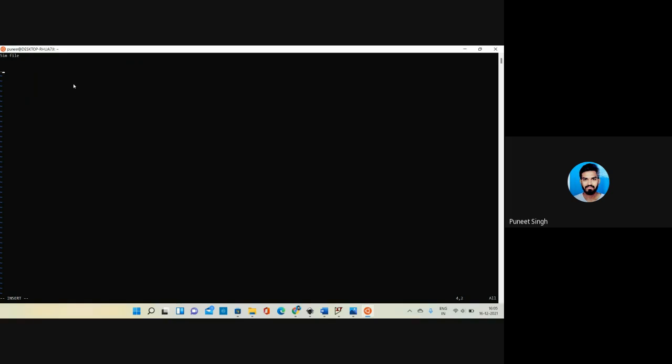First, we have to include the technology in which we want to simulate that file. So I am using the TSMC 180 nanometer .lib, and we have to include that file also.